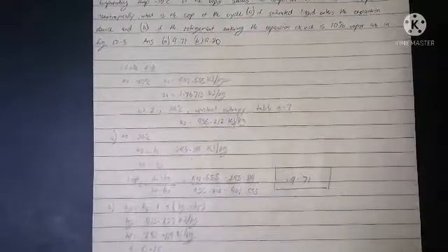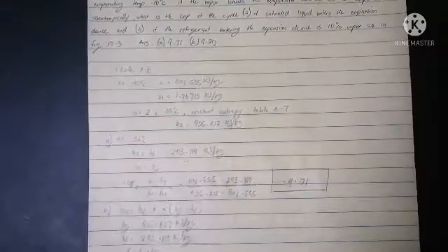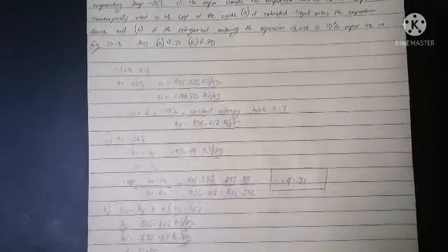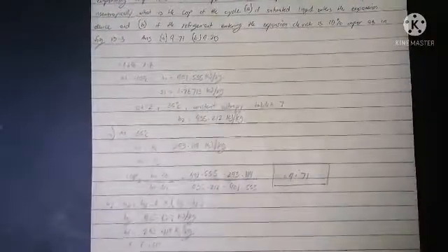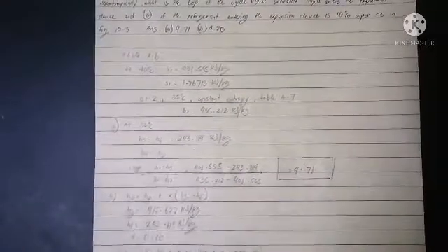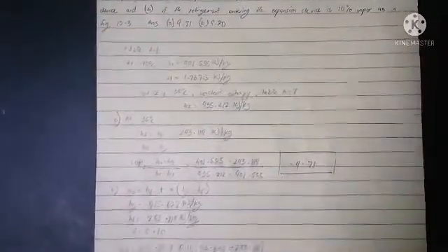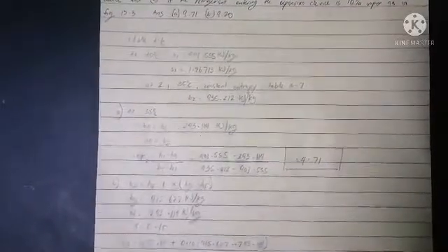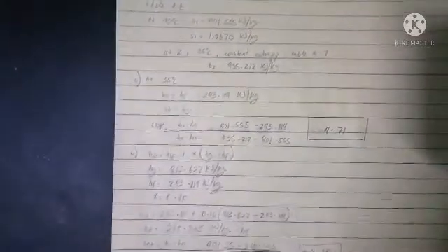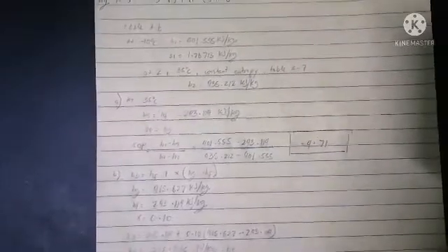So at Table A6 at negative 10 degrees, h1 is 401.555 kilojoules per kilogram. Our s1 is 1.76713 kilojoules per kilogram Kelvin. So at 35 degrees Celsius at constant entropy from Table A7, h2 is 435.212 kilojoules per kilogram. So at 35 degrees, h3 is equal to h_f equal to 243.114 kilojoules per kilogram. So h4 equals h3, so COP equals h1 minus h4 over h2 minus h1,